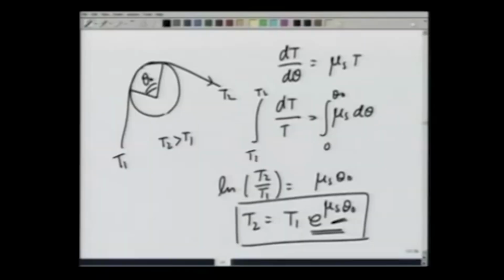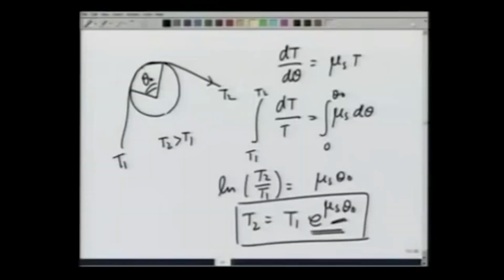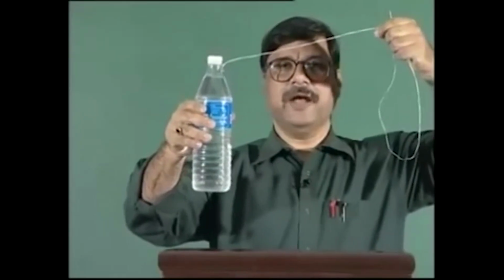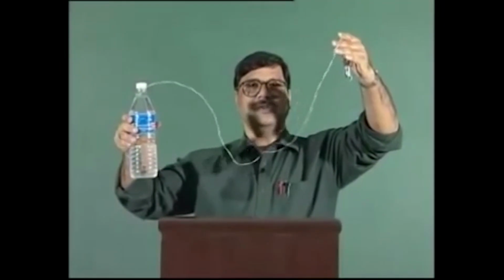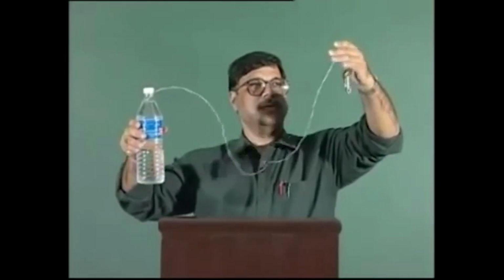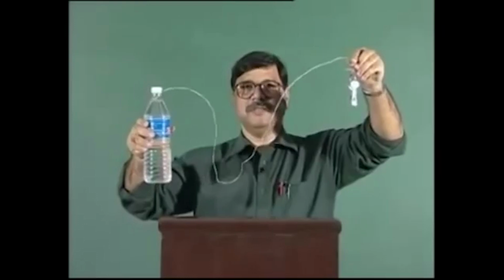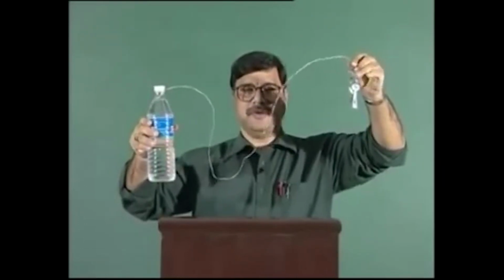It will not move. You see, because of this exponential, the force difference is quite large even for very small mu s. Let me show this to you by a demonstration. Here you see what I have done is taken a bottle filled with water. This is about a liter of water, so this is about 1 kilogram, and I am going to balance this with a very small mass on the other hand, which is just this bunch of keys, and you will see that the two will balance because of the friction.